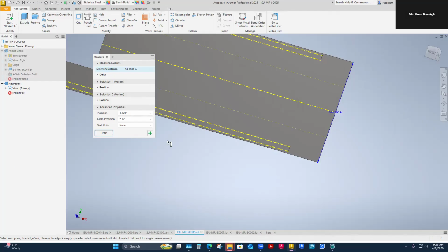This is what new people to drafting really struggle with, and new engineers do as well. They are not paying attention to what materials we use at our company and what we can get, instead of getting special size sheets and designing around those constraints. Here, I just have to be able to get an 8x4 sheet, which is a really common size, so I'm well within a normal size piece of sheet metal. But you have to pay attention to that.